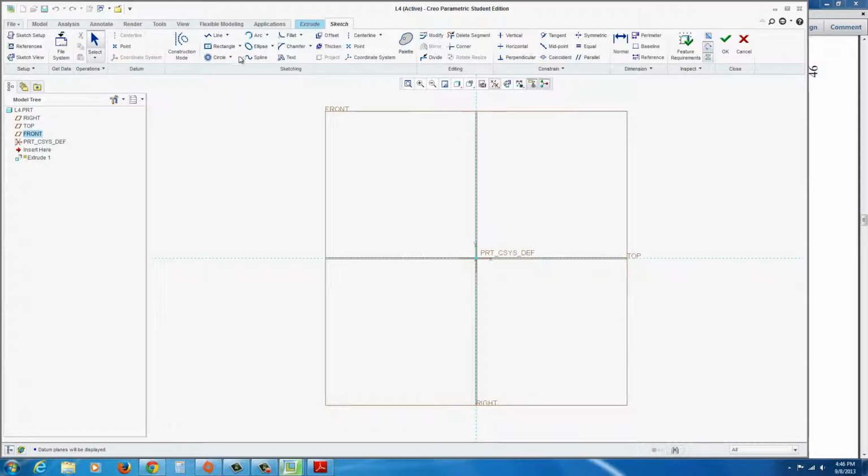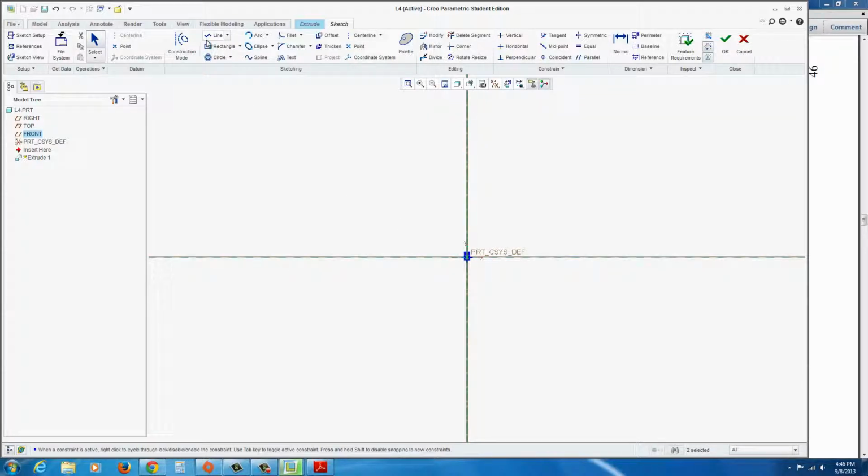and we'll proceed first by drawing a center line in the middle, a vertical center line. You can zoom up to that and just use the line tool. Now be careful here when you're drawing the line. Don't let it lock into this edge right here, this horizontal line. So go a little bit below it and just drag out a short little angled line like that. Have it cross through. And then middle click a couple times.